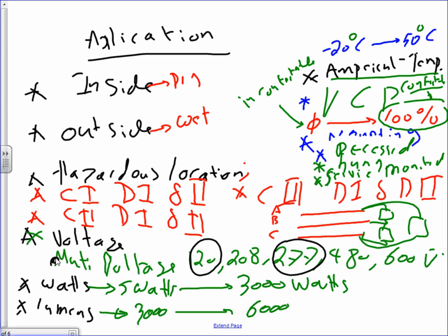I talked about circuiting, guys. Here's how you can set it. Typically, this is how you circuit your lights. This is face-to-face circuiting. If I want to burn, these are 480. Here's my 480 volt. I bring phase A and phase B to the first fixture, phase B and C to the second fixture, and phase A and C to the third fixture. Can you guys see it's like a three-phase connection? Three fixtures, three-phase connection. That's typical for high, 480.